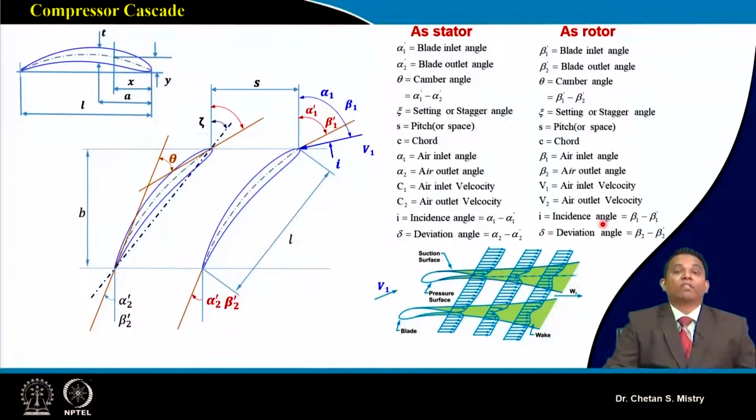Remember, you have studied this kind of logic for wings in aerodynamics, where we define it as the angle of attack. But when discussing turbo machinery, for axial flow machines or radial machines, we do not call it angle of attack. We call it the incidence angle. So do not confuse angle of attack with incidence angle. Now, this is representing my blade, and as we have discussed, this is the velocity with which my flow is striking the blade.